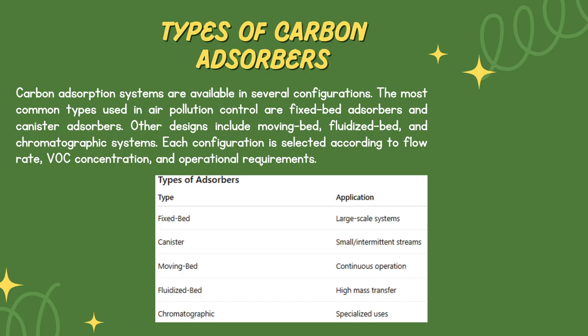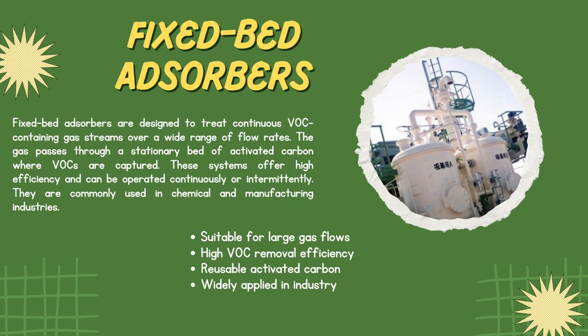Here are the types of adsorbers. You can see the fixed bed is applied in large-scale systems. The canister is for small and intermittent streams. The moving bed is for continuous operation. The fluidized bed is for high mass transfer, and the chromatographic is applied in specialized uses.